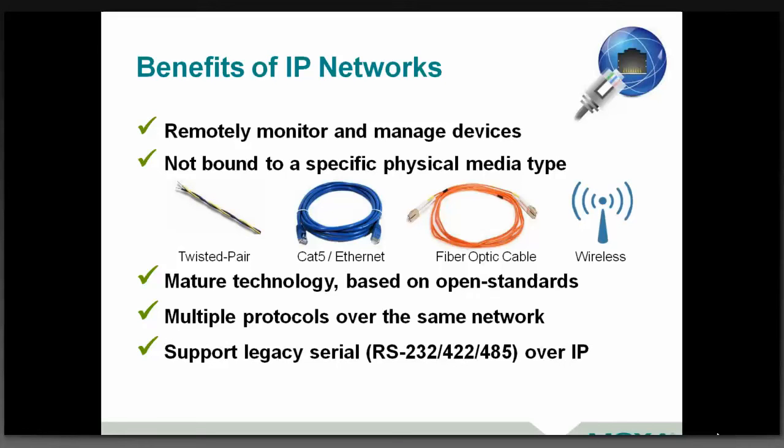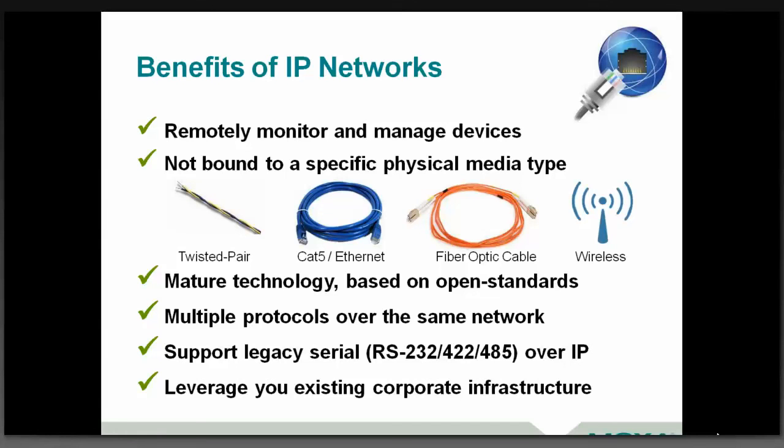And lastly, and I kind of got ahead of myself here, if some of those assets are serial-based legacy assets, power monitoring, or maybe some instrumentation, or maybe a PLC, even those old technologies can be tied in with things like gateways or device servers to integrate that legacy serial equipment over Ethernet and IP networks. And the whole core of this is how much can you utilize what you already have in place to be able to build upon that, right?